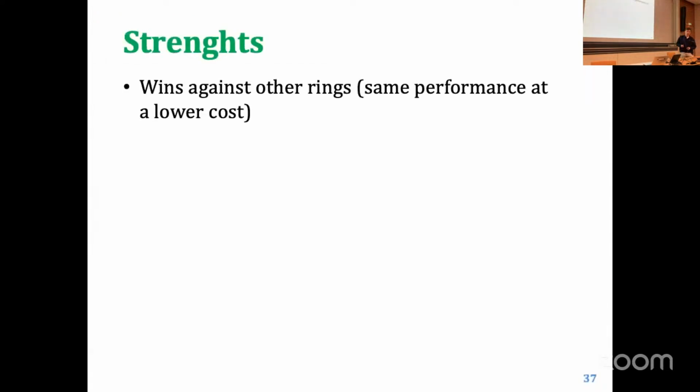So, of course, I think one of the first strengths that comes up to my mind is that this design beats its baseline and all the other ring designs if we compare power consumption and performance, because we basically have the same performance at a much lower power consumption. Its design is extremely simple, as we've seen, and the beauty of it, I think, is in the fact that we are using deflection, which is commonly a very hard strategy to implement. But with rings, it is actually very easy, because if the new data cannot join the ring, then it just does another loop.